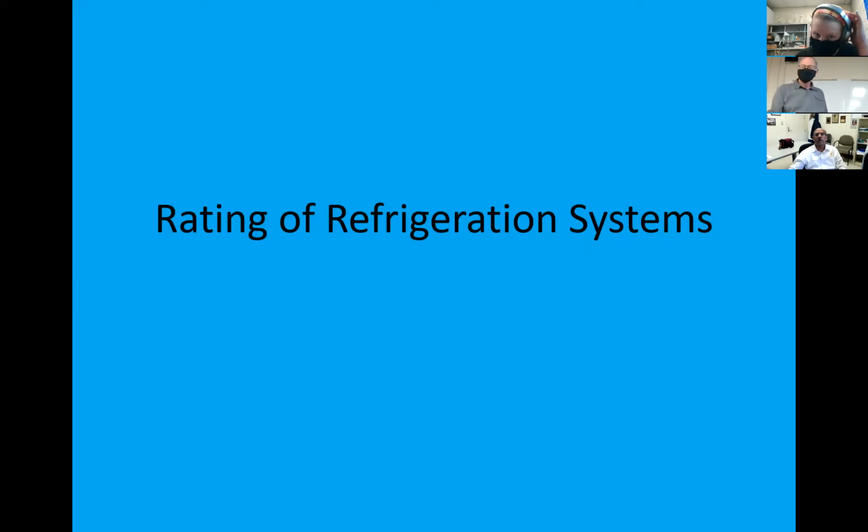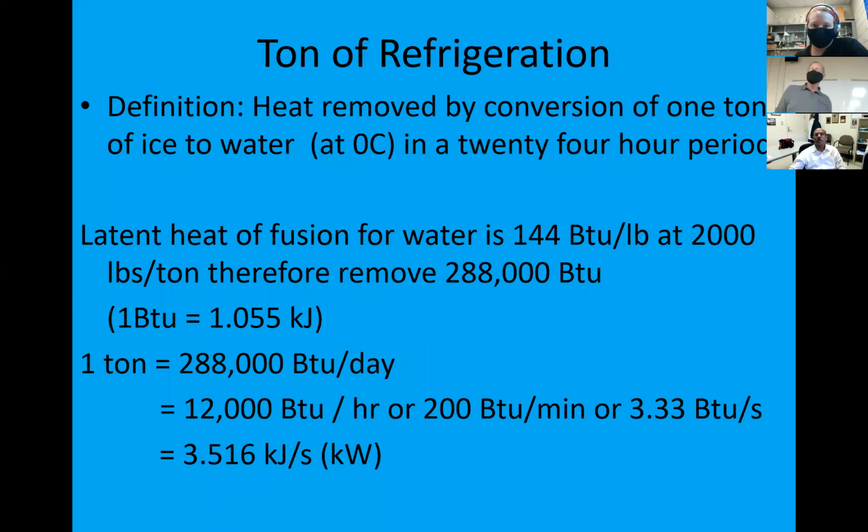Okay. Refrigeration systems, how do we rate them? How do we compare them? You go to buy a car, what are you thinking? Horsepower. Well, with refrigeration, we want to talk about tonnage. And you rate refrigeration systems on how many tons of cooling it is able to deliver in a 24-hour period.